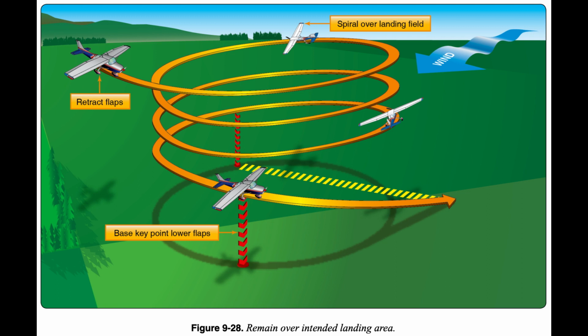Instructors need to stress during their instruction that pilots cannot dive at a field and expect to land on it. During all simulated emergency landings, keep the engine warm and cleared. During a simulated emergency landing, either the instructor or the pilot should have complete control of the throttle. There should be no doubt as to who has control, since many near accidents have occurred from such misunderstandings.